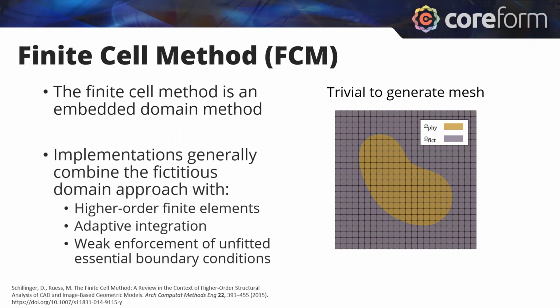A lot of the finite cell approaches have demonstrated or utilized high order finite elements, sometimes B-spline elements with hierarchical refinement. They've used adaptive integration at surface boundaries, and they've used weak enforcement of those immersed Dirichlet boundary conditions.